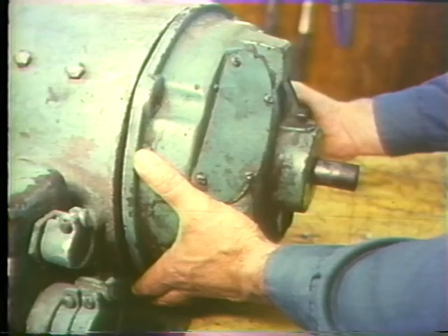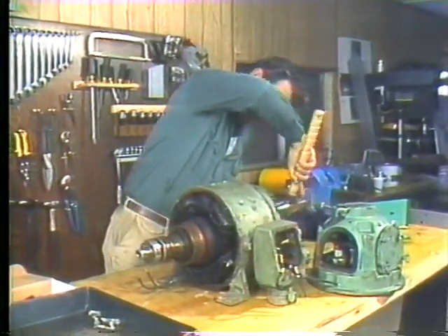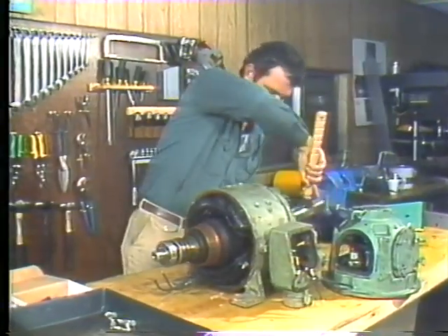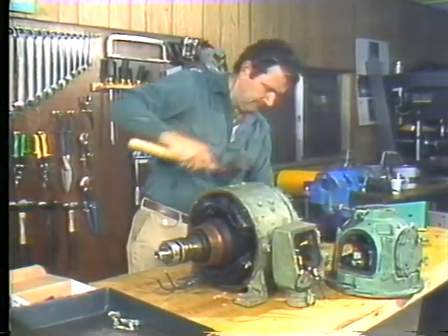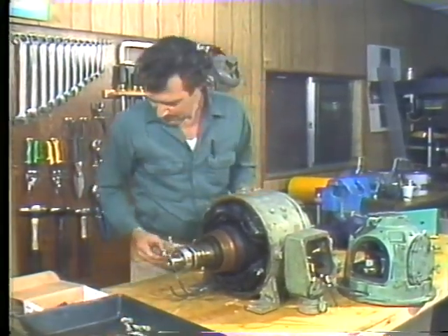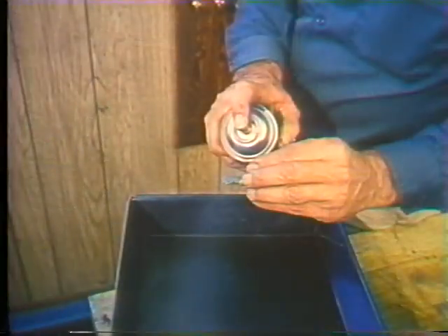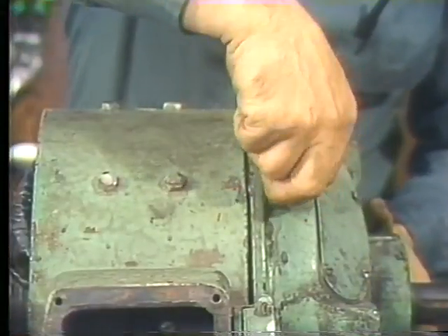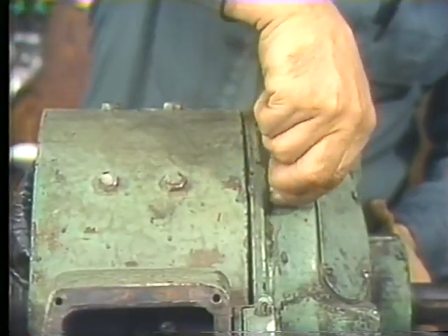Line the bearing housing up with the bearing. Then tap the soft-faced hammer against the end bell until the bearing is in its housing. Before you line up the punch marks and start the end bell bolts, lubricate the bolt threads. Don't tighten the bolts yet, just start them so the end bell won't slip off the bearing.